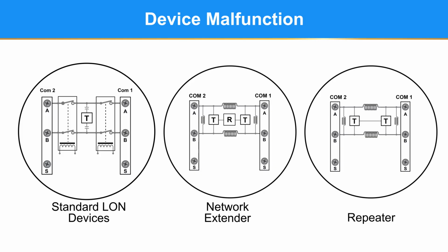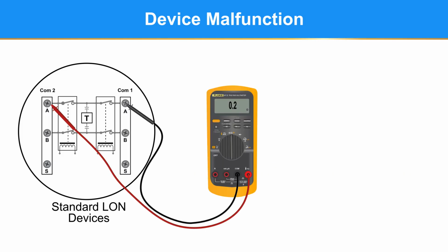And then there could be an inadvertent system alarm, as some output devices could be configured to trip if there is a loss of power, and you are going to have to remove power to swap out the device. It is best to try ohming out suspect devices first.